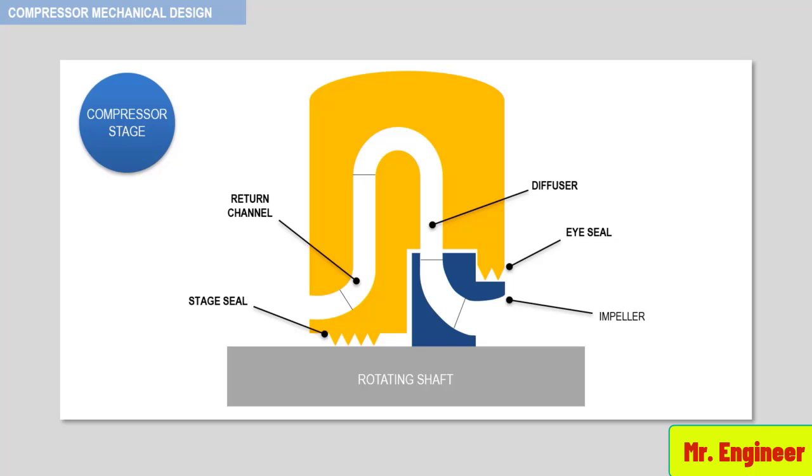Diaphragms can be manufactured of either cast iron or cast steel. Both materials are acceptable. However, in the event of severe axial rubs caused by excessive surge, cast iron diaphragms can crack and will require replacement. Since centrifugal diaphragms are rarely spared, failure will cause long periods of downtime and loss of product revenue.